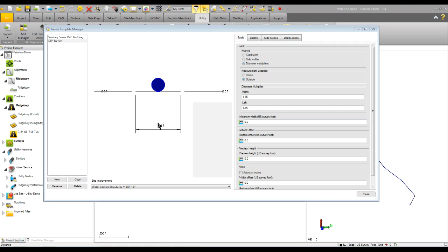You've got to keep in mind this is feet, not inches. We have an 11-inch outside diameter of our pipe, and again we're basing this off the bell casing, and we need 16 inches additional. So that's 27 inches. So if we use our calculator and we take 27 divided by 12, it's actually 2.25. Rounded up is 2.3. So we know that that's going to be the proper trench width.